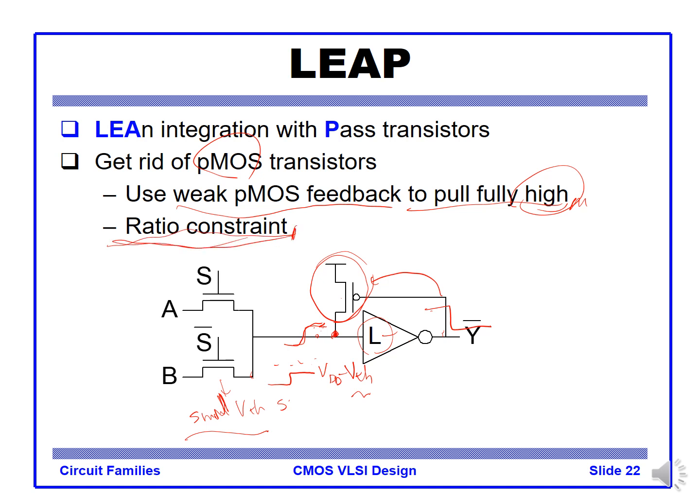The ratio is critical, because this PMOS keeper device needs to be weak enough so that the NMOS driving here can overcome it. Typically the inverter will drive through this device. So this NMOS and the pull down device at the same time need to be stronger than this PMOS device, right? So the PMOS keeper device should be small enough.